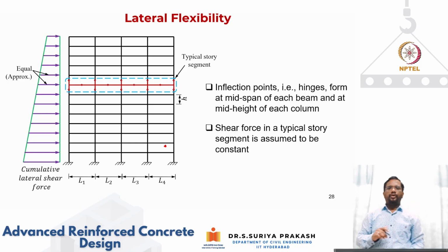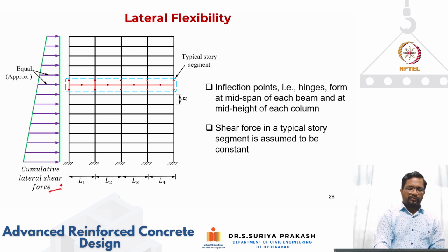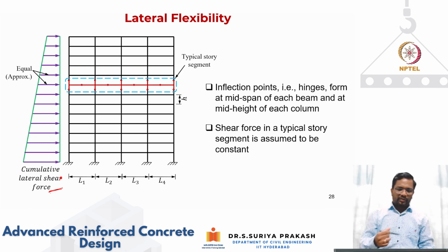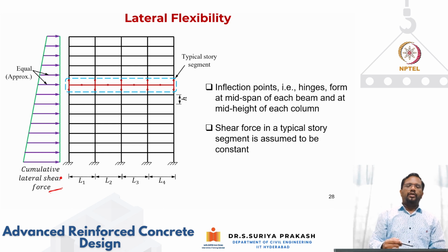So now, a very important thing is, let's say, practically considering a frame, and I wanted to calculate the lateral flexibility for a particular story. Okay, so let's say this is some multi-story moment resisting frame, and it is subjected to this kind of cumulative shear force. When it is subjected to lateral force from wind or similar, you can calculate the shear force at all the story levels, right?